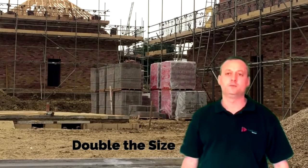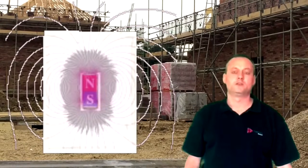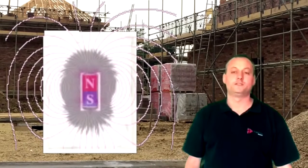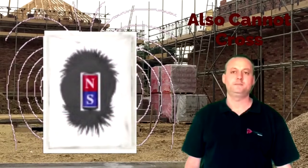Its new resistance would be 5 ohms. We went on to look at permanent magnets and magnetic fields, and they have some rules. These rules could come up as exam questions. Lines of magnetic flux flow from north to south. They take the shortest possible route from north to south. They cannot be broken, only reshaped.